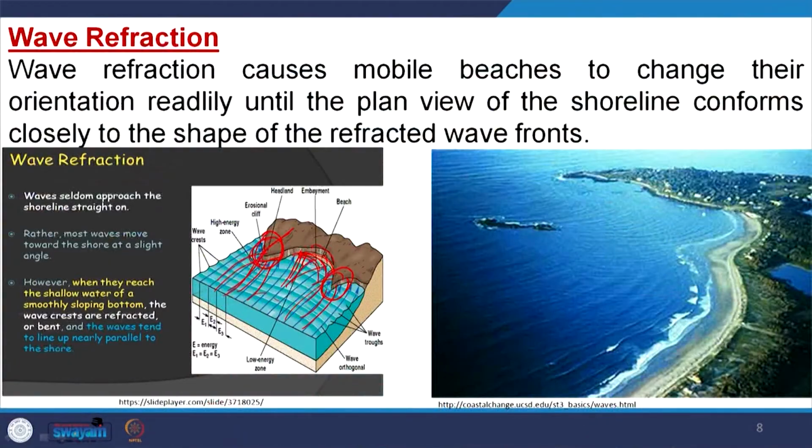For example, if you see here, these are clearly the refracted waves like this, and the beach shape is also like that. Similarly, here the refracted waves are like this, and the beach is of that shape. So with geological time, the beach takes that shape from an aerial view, following the shape of the refracted wave from the breaker zone.